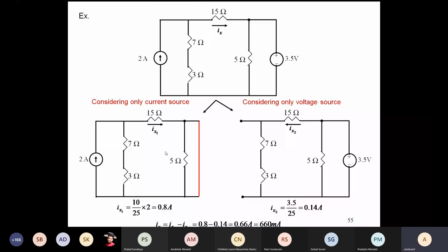Yes, sir. So you must understand the significance of short circuit, which is zero resistance, and also open circuit means it is just hanging in the air. So then there will be no circuit, no current through it, because it needs the closed path. But you can measure some voltage here. In the open circuit, if you have a meter, you can measure the voltage. But we are not concerned about voltage. We are concerned about current, which needs a closed path.